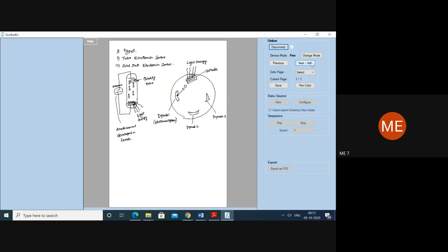Further, we have placed what are called the photo multipliers, the dynodes. This dynode observes the secondary electrons liberated, and since it is kept at a positive potential, it attracts them, multiplies the secondary electrons, and accelerates their movement. Then these secondary electrons get attracted by another dynode.